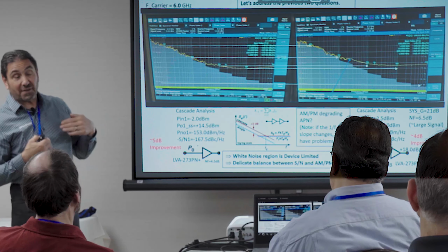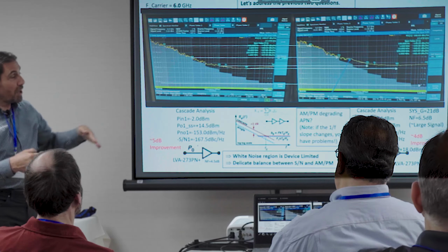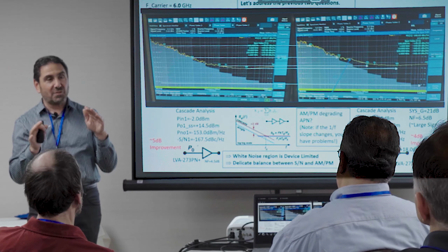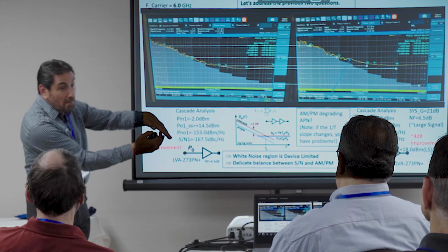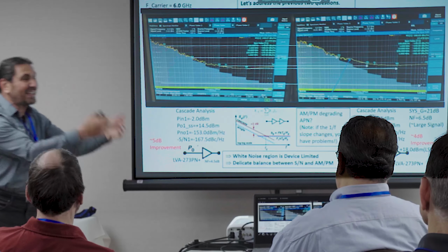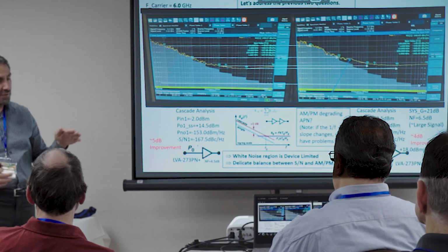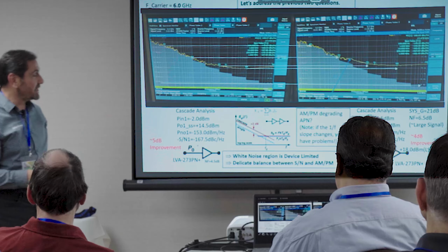We have equalizers that are matched. They give you a positive going slope. If you want a negative going slope, you can use a reflectionless filter for that. You find a low pass that's got about the right response, you use it in that region, and you get a sloped filter that's matched. You're not reflecting with a conventional filter back in. You're using a reflectionless filter to generate a negative going matched slope equalization.